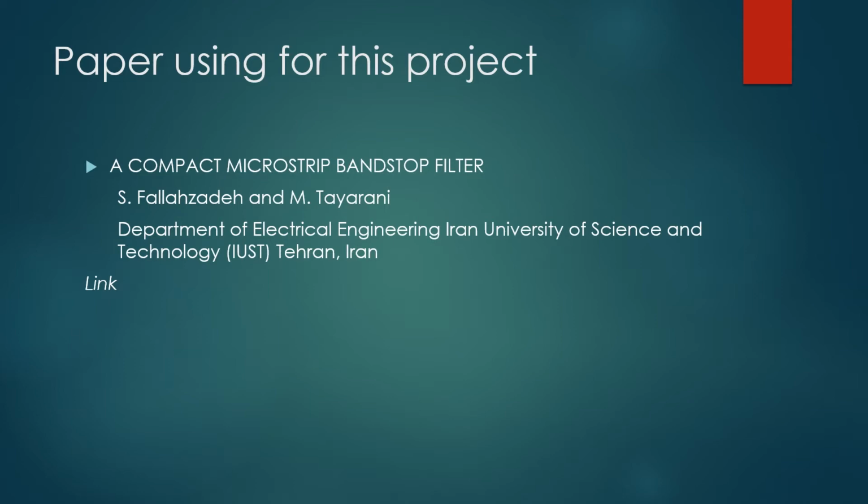In signal processing, a bandstop filter, also known as a band rejection filter, is a filter that passes most frequencies unaltered but attenuates those in a specific range to very low levels. Bandstop filters can be made by placing a low-pass filter in parallel with a high-pass filter.